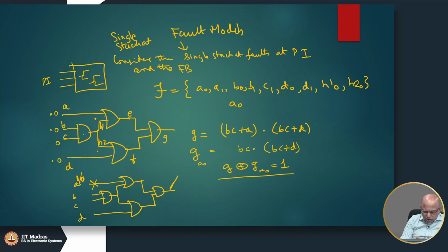Now, if I put 1/0, it means in a good circuit I am able to put a 1 properly, but if it is a faulty circuit, it has a defect. As a result, it sees a 0 here. Now, what should I put here so that the effect of this fault goes out? After all, we cannot directly look at this value. I can't put a multimeter here and check what is the value here. I have to observe it only here. So, this is the observability point.